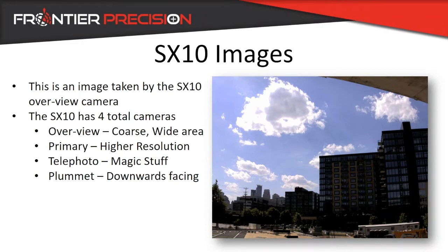In this case, it's a video plummet. It's downward facing. It allows you to take an image, but also to see the plummet position of the robot. So you can document that, yes, if you're doing a traditional backside setup, I was indeed over this monument or my control point, and have that for verification, and then continue on with your backside reference.